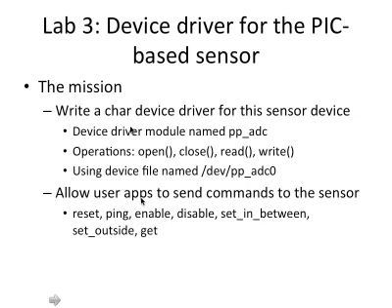This module will support these operations: open, close, read and write. And this is a character device, by the way. Associated with this device driver, we will create a device file named /dev/pp_ADC0.